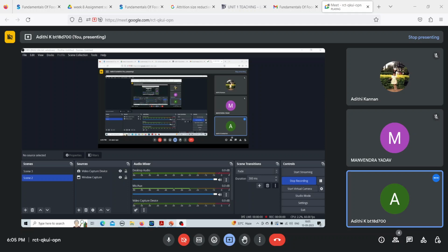So if you remember what we discussed about work index, it is used in Bond's law, where m is equal to 3 by 2. That is, your energy consumption is directly proportional to root of the surface to volume ratio. So m is equal to 3 by 2. So when you look at the term work index, it means you need to use the Bond's law.